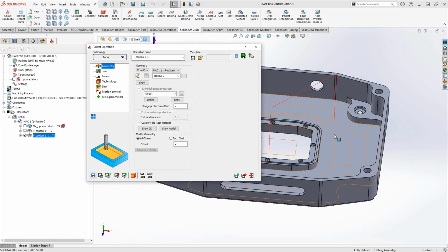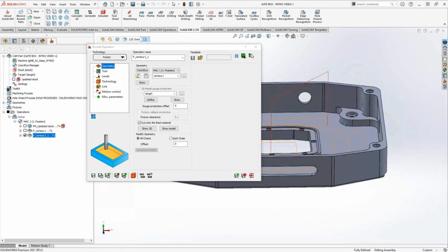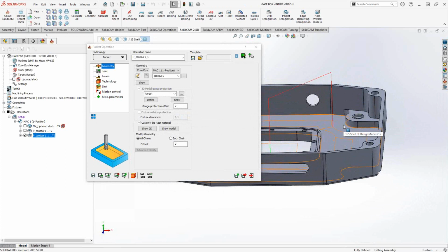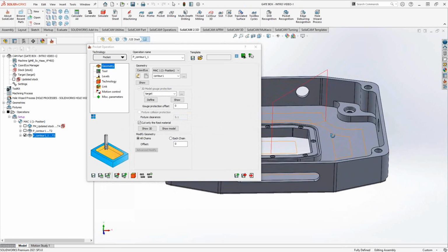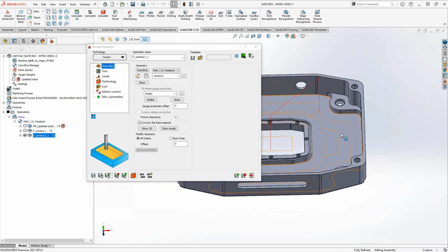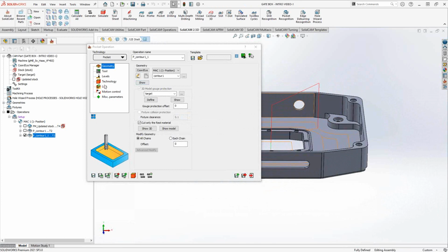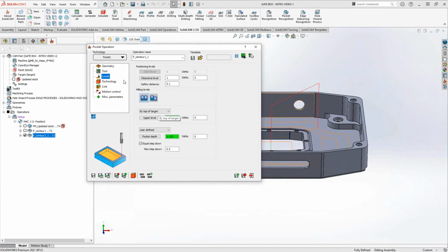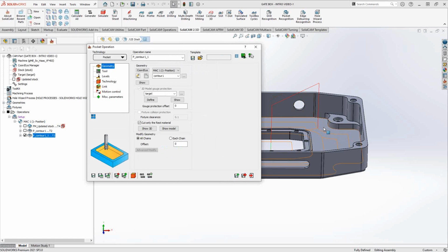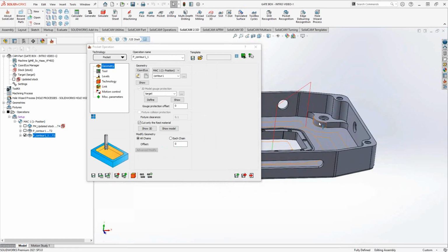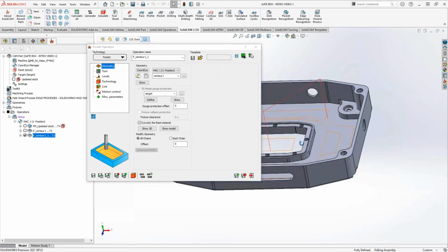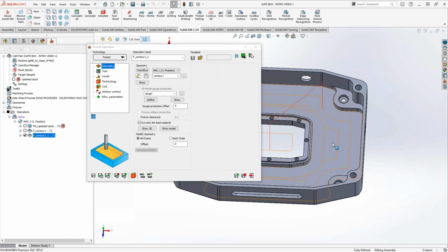With the target protection turned on, it recognized from my previous toolpath, same tool, same chain, but with the target protection turned on and going to the lower level, that it didn't have to do all the steps. The levels are still the same, but it recognized that in this Z level, it only had to go from the top of that tab down to that face. So I was able to continue the toolpath.